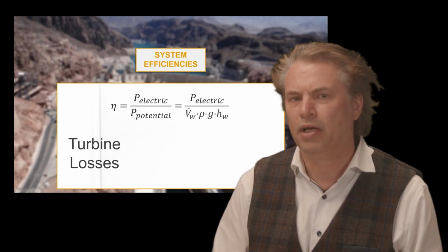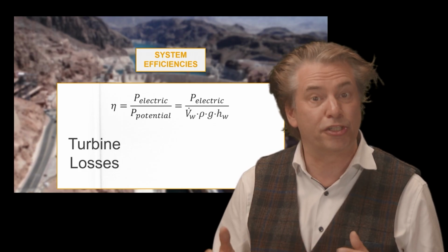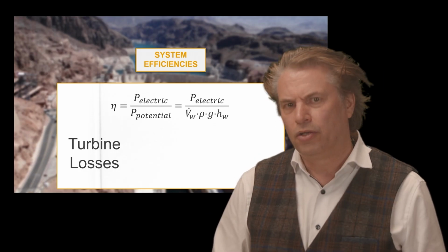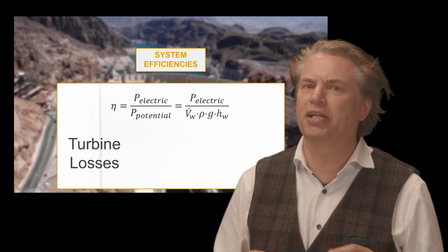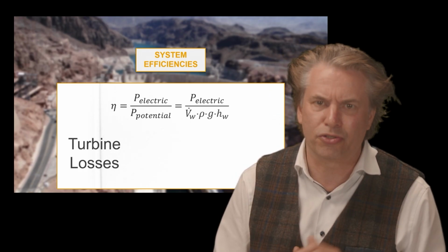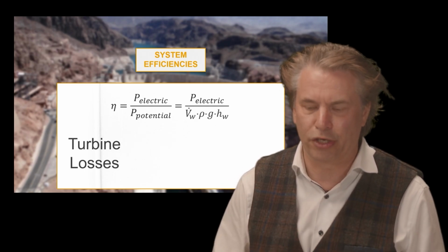As an example, a typical Francis turbine can operate at efficiencies of 90 up to 95%. The loss mechanisms of turbines are typically hydraulic losses, vortex rope formation, leakage losses, mechanical losses, and incomplete velocity reduction.